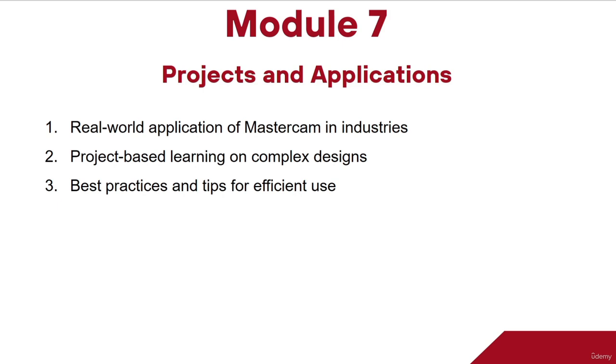After completing the 3D module, we stepped ahead towards the most complex geometries, which are machined by multi-axis. We discussed how we can create multi-axis toolpaths in Mastercam, including 3+1 and 3+2 axis toolpaths, rotary axis toolpath, and 3+2 automated roughing, which is interesting for those who want to do automatic multi-axis programming.